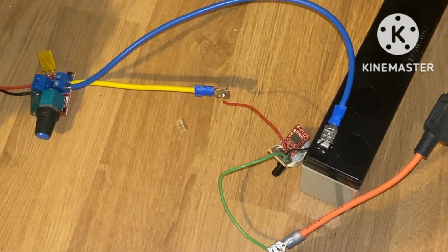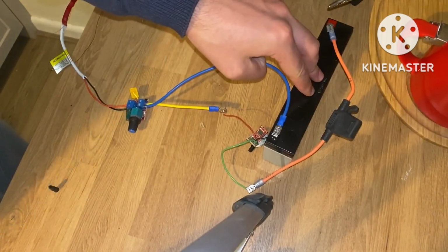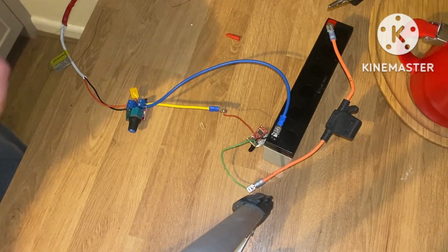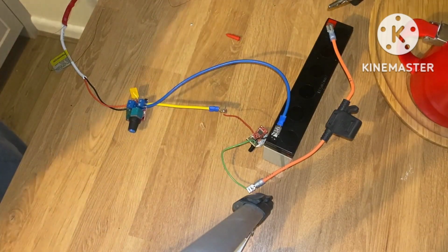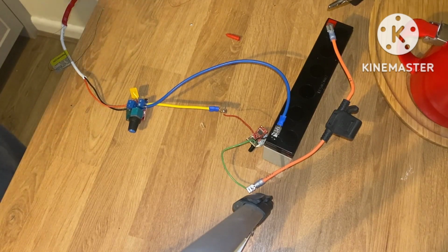Now, why do I need it? Well, it all comes down to a few different things. Firstly, batteries are very good at giving you stable voltage, but if you pull a lot of current from them instantaneously, their voltage can dip slightly. And it's not an uncommon thing. If you've ever seen a car turning its engine on when the headlights are running, you'll see that the headlights dim as the engine turns on, and that's because the battery's pumping out loads of current getting the engine going.